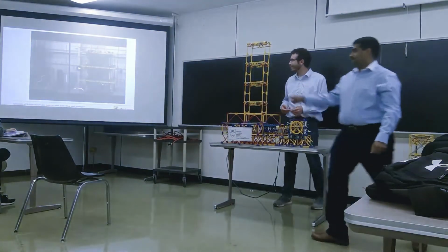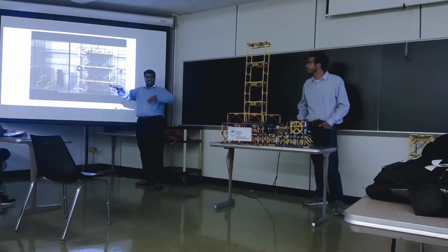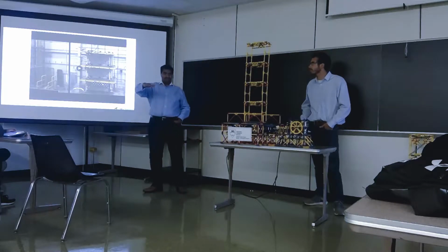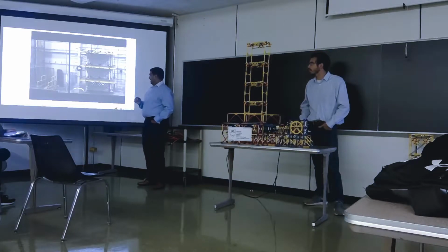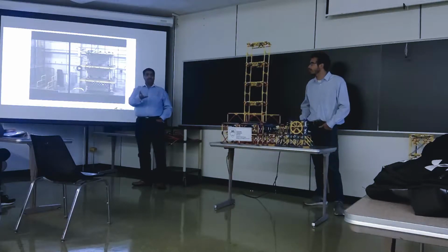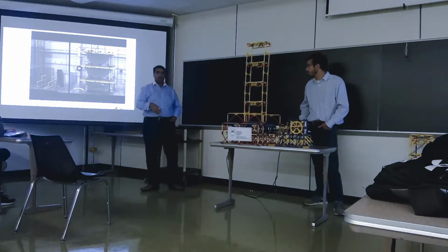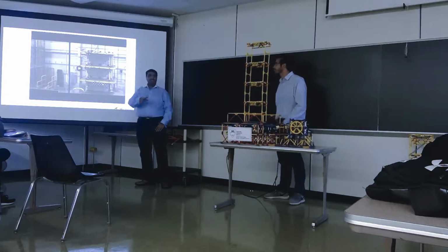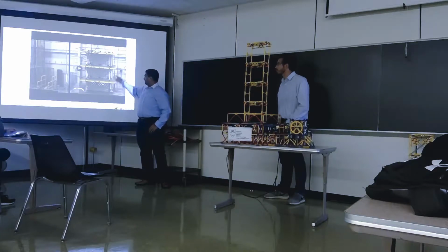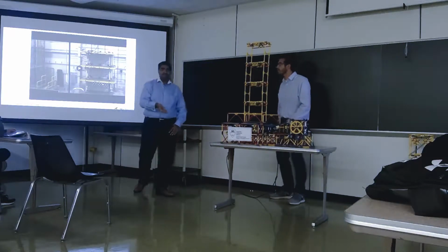Let me explain a little bit what's happening here. So this bottom one you see is the shake table. That's vibrating in the horizontal plane. And this is a building that's responding, right? When we do research, we try to change the stiffness of the system by changing the poles and what type of material we use, how we change mass, columns, and so on. And then as the stiffness changes, the natural frequency changes, right? And there are accelerometers, sensors over here, measuring the response of the system to an input.